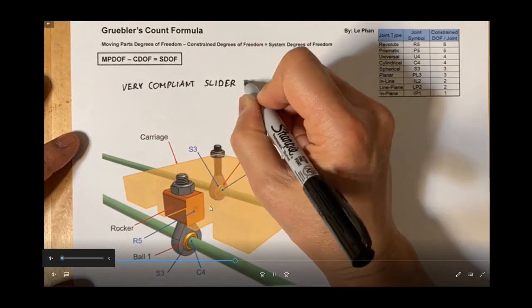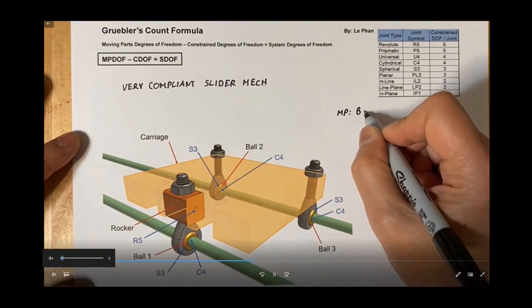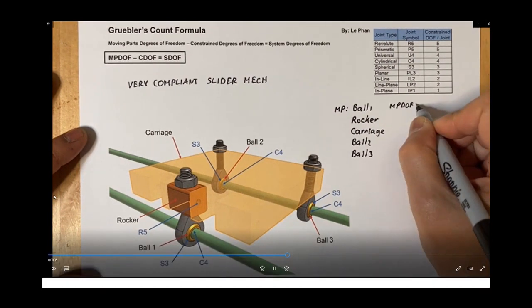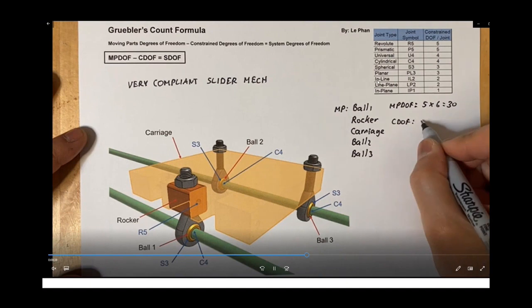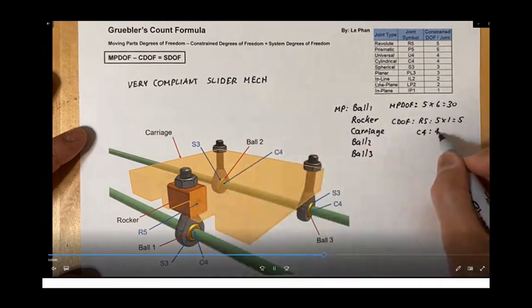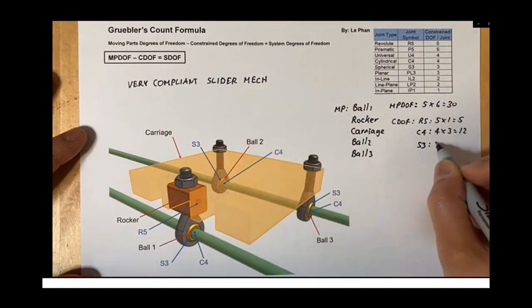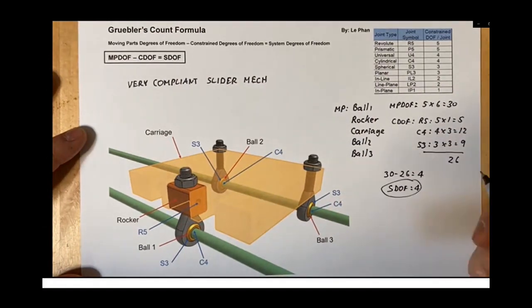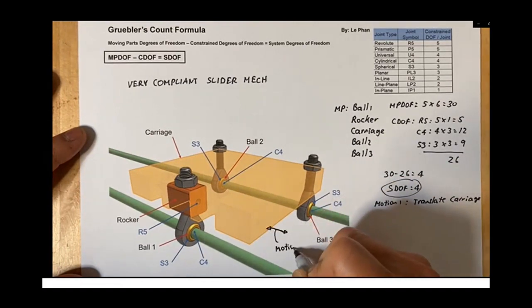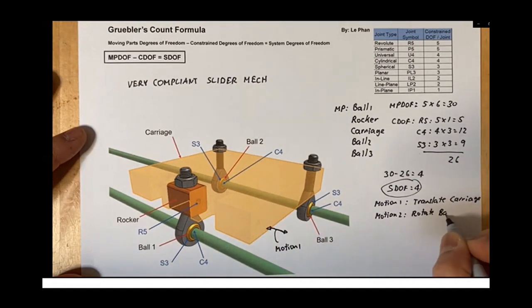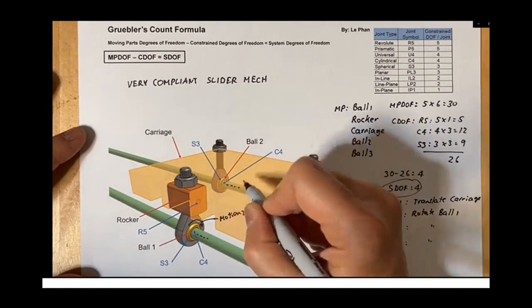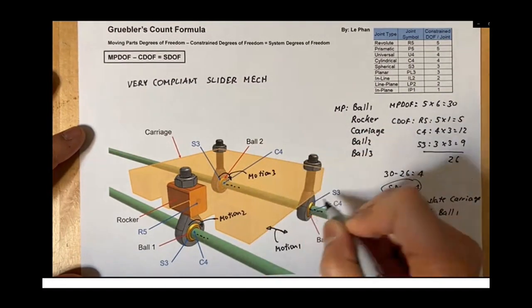Now, does anyone know the tolerances that are required for a THK rail between the parallelism? Does anybody know that? What are they asking for? Do you guys remember? I used to design slide tables just like this, and you're exactly right. They would get into a bind, so the technician would have to put enough tolerance in the bolt pattern to make sure everything was parallel and tested. Right. And they were asking like thousandths, within distance of one another and parallelism and everything. And after a while, when things bend and wear, it's going to get out of place too.